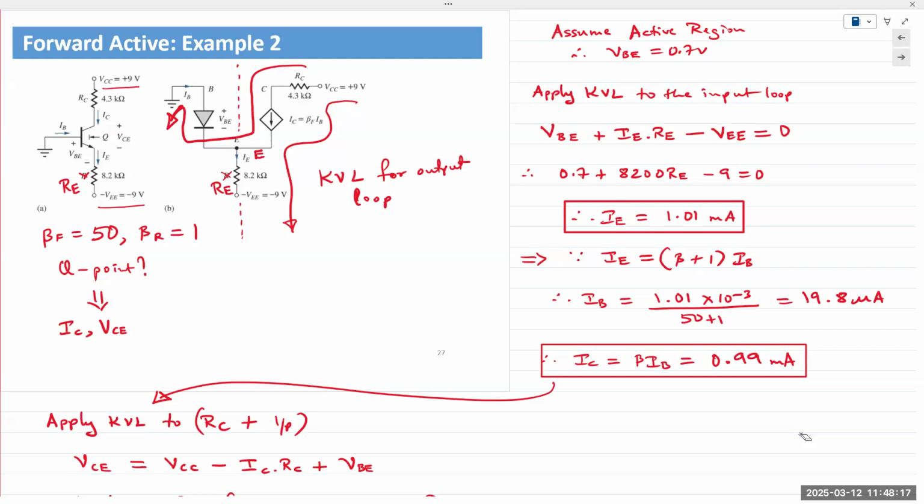If it's forward bias, saturation mode, we can put a diode in there, and that would work. But here it would be a reverse bias diode in place of that dependent current source. So again, the answer is yes, we could put a diode in there and show it's like reverse bias, but then that wouldn't describe the operation of our BJT. Does that make sense? It is a PN junction, but it wouldn't describe what's happening at the output terminal. The output is best described as a current source.